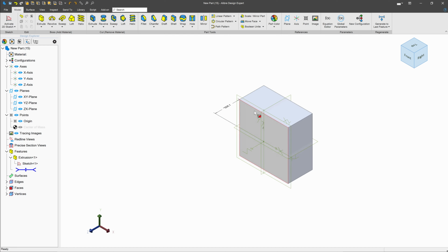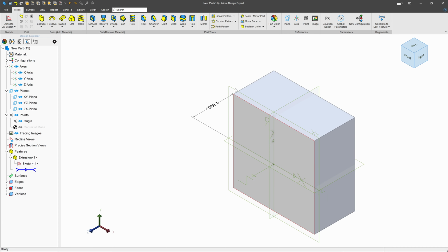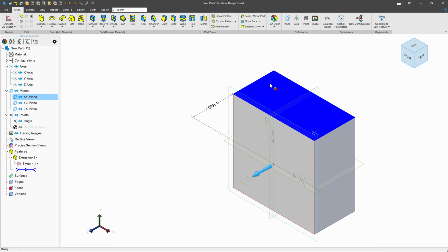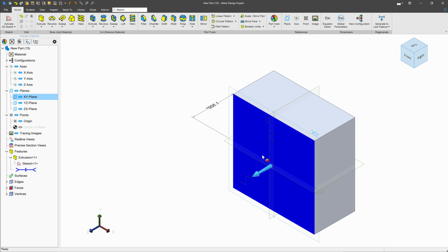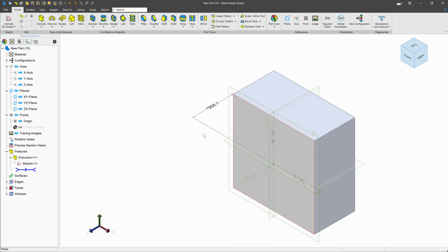So you'll notice I didn't do midpoint or midplane. I did it straight off the XY plane. So if I were to superimpose my pawn model into this model, the pawn would be half out and half inside because the pawn was revolved around the y-axis from the XY plane. So the pawn will sit half in, half out, and that's what I'm actually planning on. So I'll save this and I'll call it tooling.